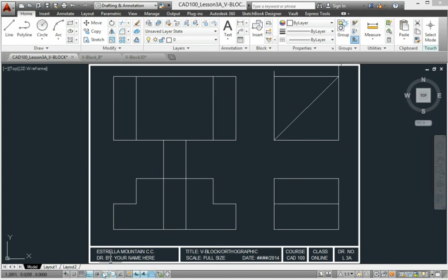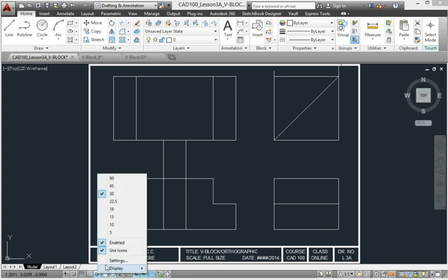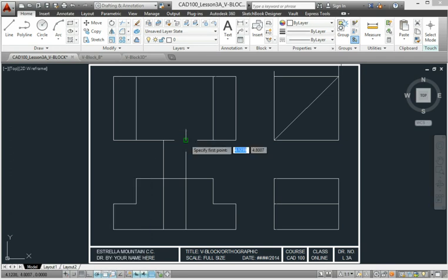To do this, we're going to remove ortho mode and turn on polar tracking. We're going to right click on polar tracking since we're using it for the first time. So with 30 degrees on, we're going to draw lines with polar aiding us to complete this quite easily. You'll see a dotted line, in this case the line's green. You're going to hover up till you see 30 degrees. When it gets to 30 degrees, that tracking line will automatically appear.